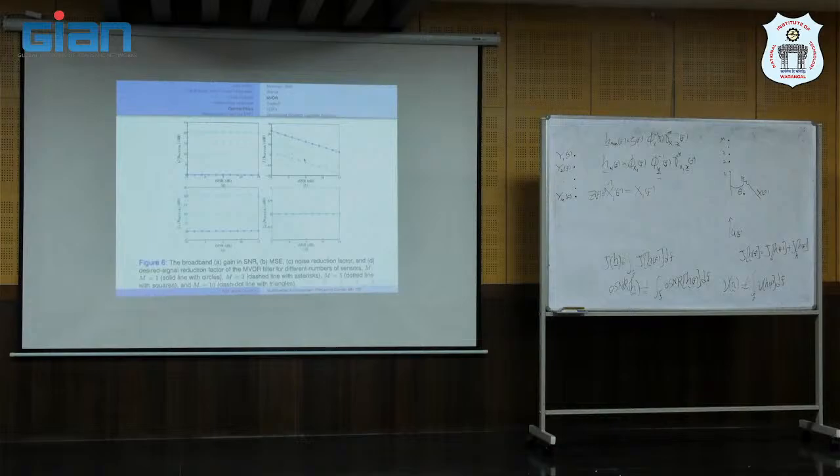Okay, the MVDR, we have signal subspace. It doesn't distort this signal subspace. So the amount of noise that is reduced or suppressed is just in the noise-only subspace. That's why it's limited in the amount of noise that it can reduce. The Wiener suppresses more noise, and it introduces in the signal subspace some distortion.